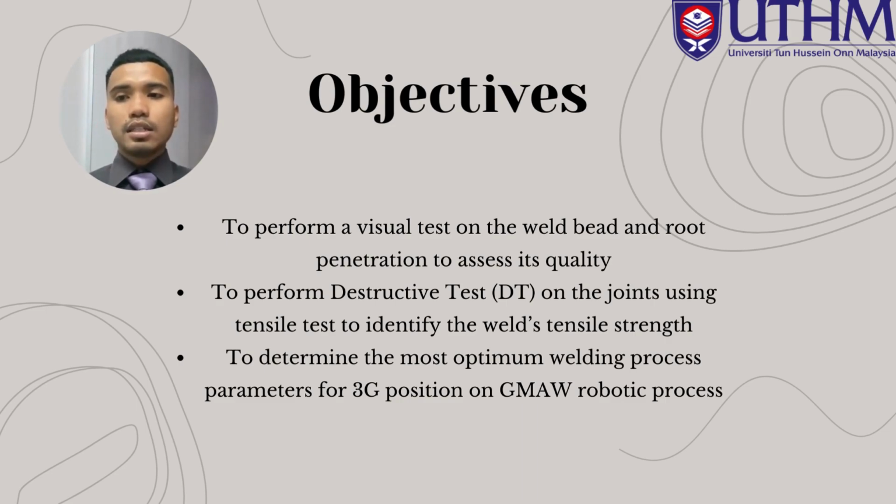And the second one is to perform destructive tests on the joint using tensile tests to identify the weld tensile strength. And the third one is to determine the most optimum welding process parameters for 3G position on GMAW robotic process.